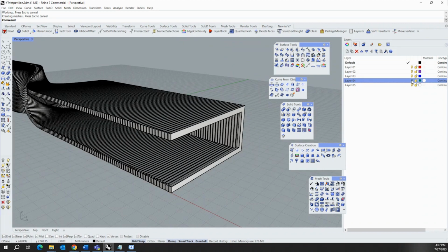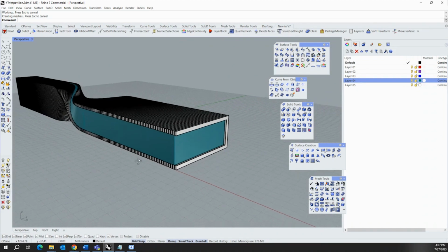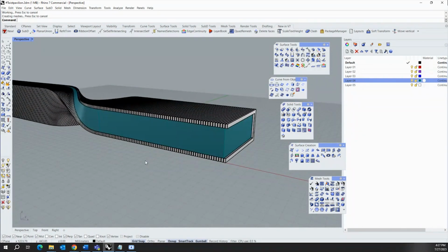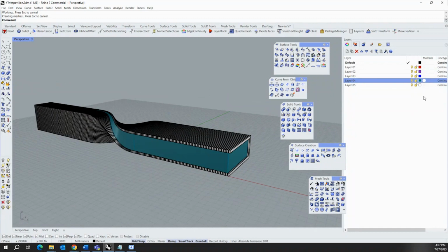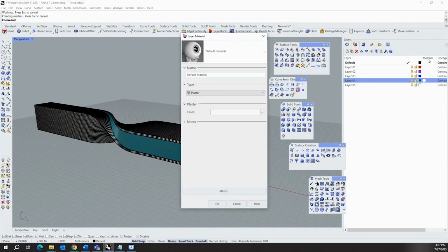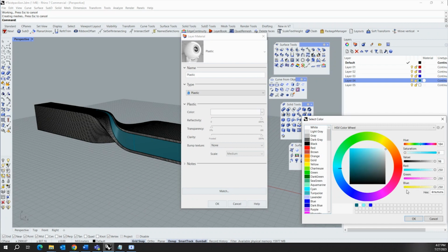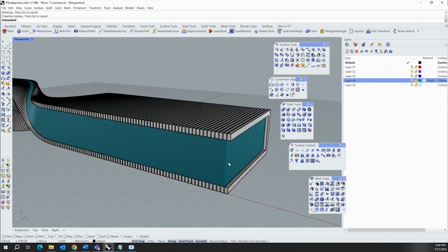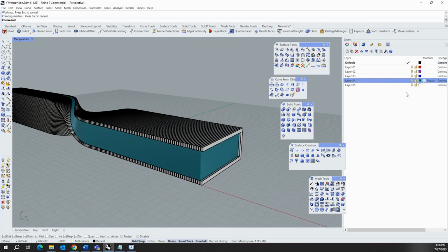So right now I'm going to switch on this glass also. And interestingly, if we need to make this building look better, we'll add some material into it. I'll go to the material in this layer command, and I'll add some material. Maybe I'll choose the color light blue for the glass. And I'll give the transparency like 50 percent so that you can see the internal pieces. Right now you cannot see, let it be like that.